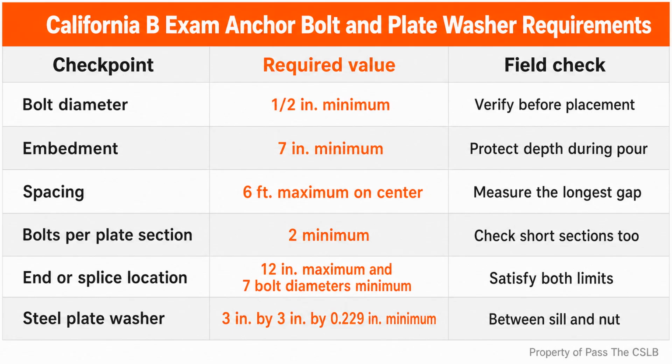The supervisor has to distinguish a rated protective cover from a bright piece of plastic that only looks protective. Formwork has to be securely anchored, guyed, or braced against collapse. Reinforcing steel must not be used as a guy or brace for frame panels or concrete forms. Steel that belongs to the concrete assembly is not a substitute for a designed and secure form bracing system.